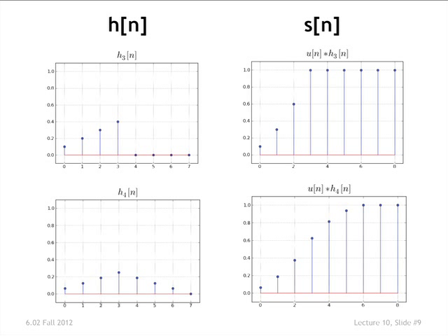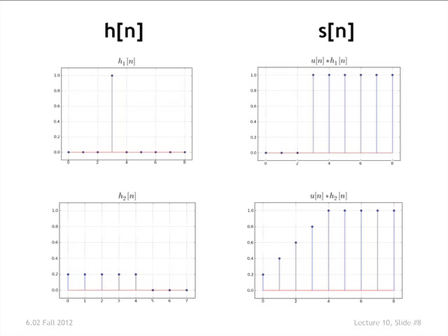Examples of this type. Now, here's one important thing for you to get a feel for. Notice in all these examples, the unit sample response settles down to 0 after some time. So you hit the system with a unit sample function at the input, with the value 1 at time 0 and nothing else, and it responds for a while and settles. Now, it's not true for all systems that they settle in finite time. A typical system might ring indefinitely, might respond indefinitely to a kick. All these examples are ones where the system has a transient and then settles down.